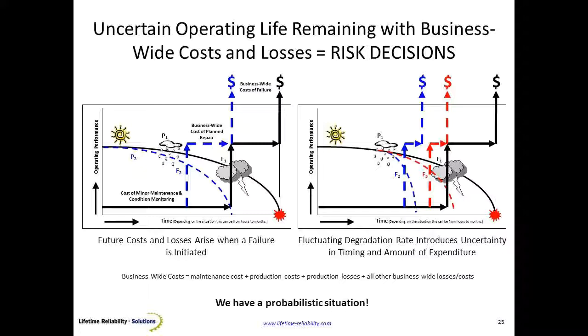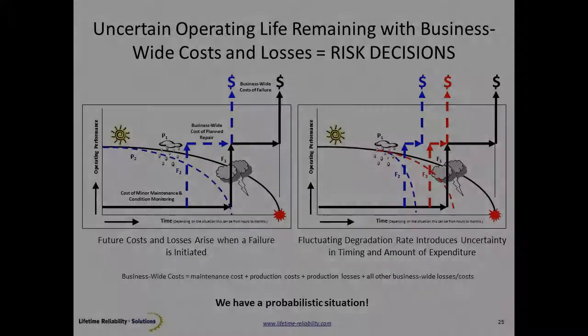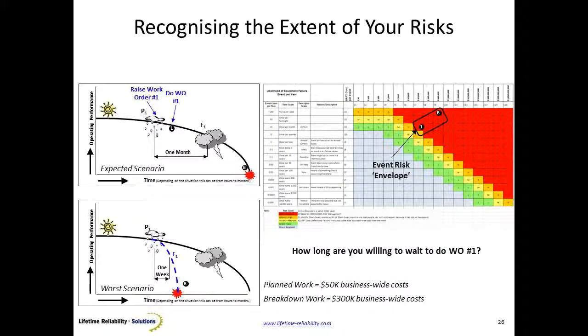So yeah, our machines are a bit more difficult to work with than simply looking at those and using them and maintaining them. There's a lot of unknowns, a lot of risks always present, and depending upon how those holes in the Swiss cheeses that we use as barriers, as maintenance, operating practices, installation practices, selection practices line up, these failures could happen at any time and could be any cost. So if I've got a risk situation, it means I can then use a risk matrix to model that situation.